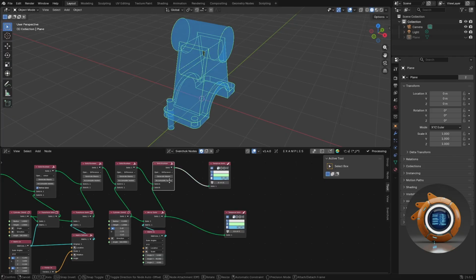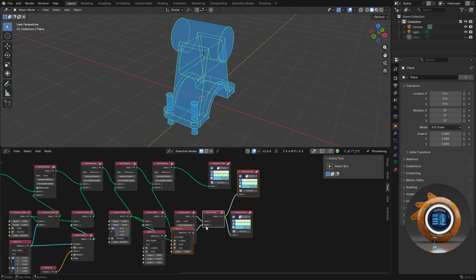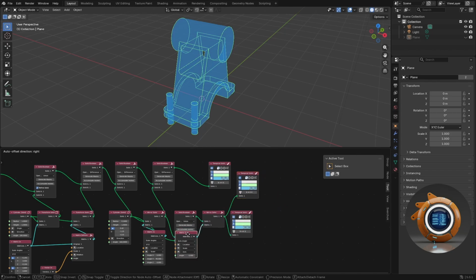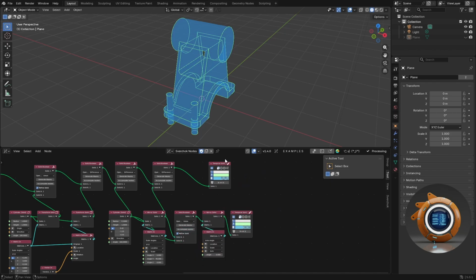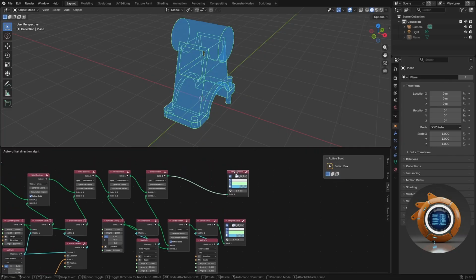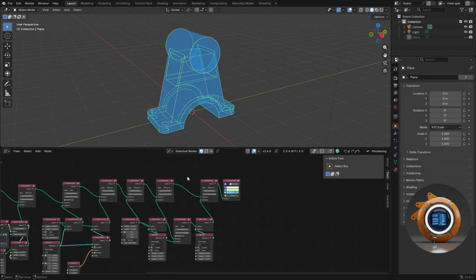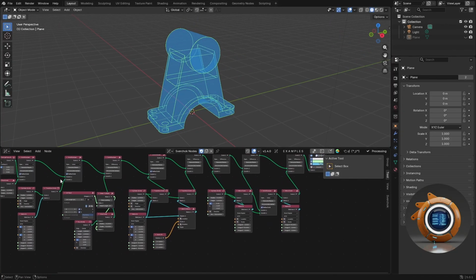Join these 2 cylinders together with a solid Boolean node. Then apply another mirror node to duplicate them on the other side. Rotating the mirror plane by 90 degrees on the x-axis. Finally, apply a Boolean difference to preview the final result. Look how clean it is. This is one of those moments where solids really start to shine, and everything just clicks.